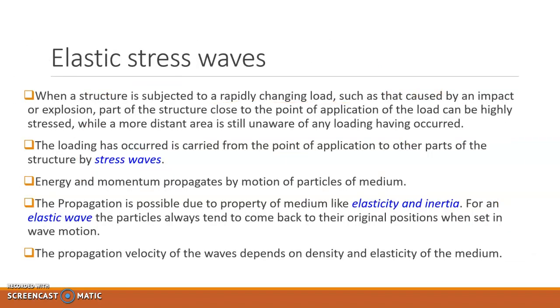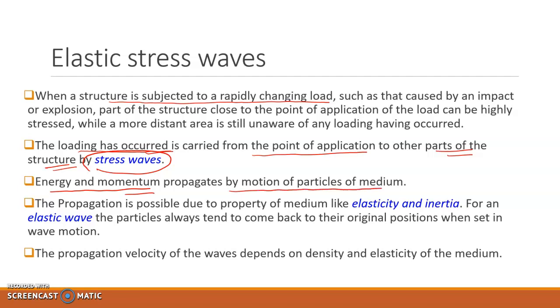When a structure is subjected to a rapidly changing load, just like in HVF, the loading occurs at the point of application and is carried from that point to other parts of the structure by stress waves. By these stress waves, the energy and momentum propagate by motion of particles of the medium or the material.